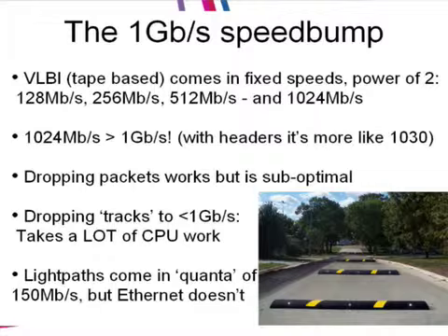The other thing is that the data we get is not just a sampled piece of spectrum, it's actually many subbands sampled at 2 bits. So we have tried to throw away one of these subbands. Unfortunately, the hardware we have generates this data in a long 64-bit parallel word. Now imagine having your CPU take these 64-bit words, take out 2 bits, slide them together, pack them together, and do this continuously at the speeds of a gigabit. This kind of bit manipulation at a gigabit is very difficult to do and really takes up a lot of CPU work. So where possible, we try and get our bandwidth in different ways.